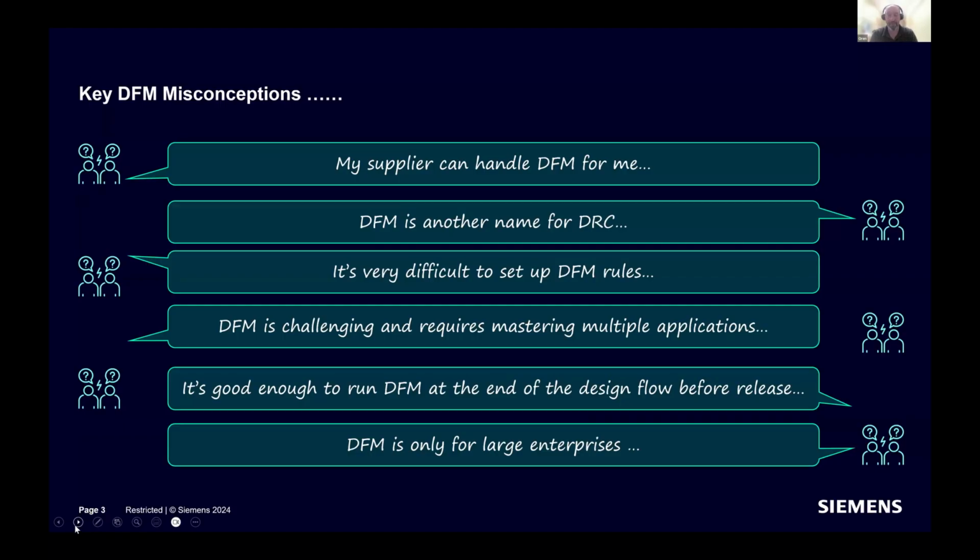Having your supplier do DFM is essential and a must, but in many cases it's a little bit too late in the game, because you've already finished the entire design. So you're still going to have to do rework, and if the design is complex, that's not very efficient. And second of all, as a designer, your objectives and interests do not always fully align with the supplier's. We'll go into that.